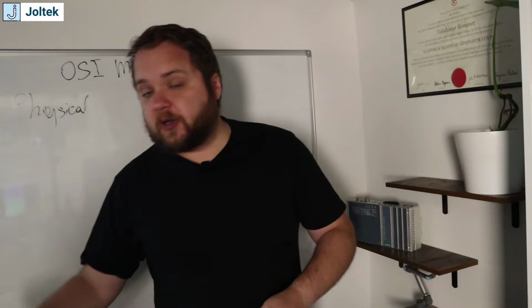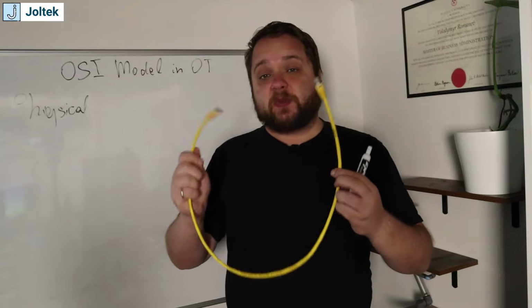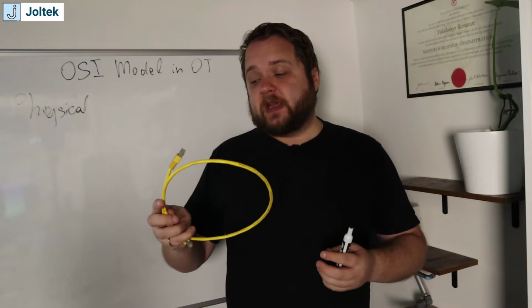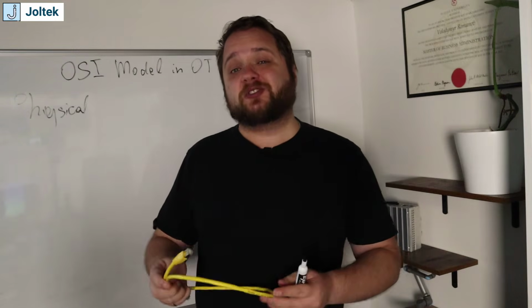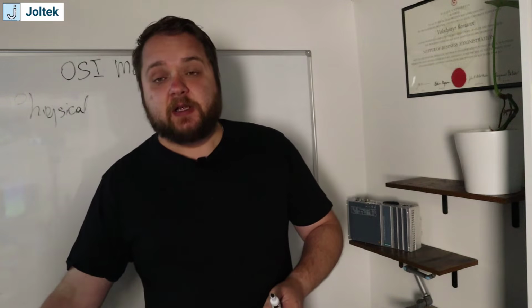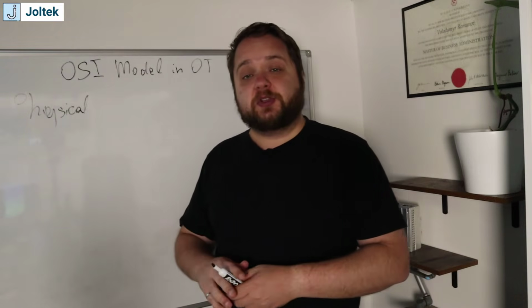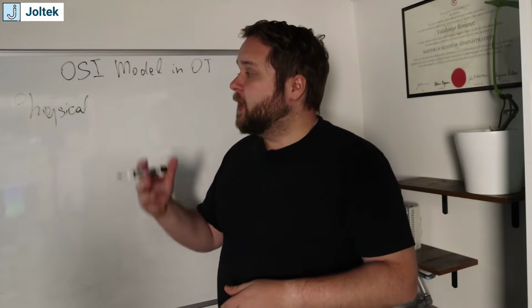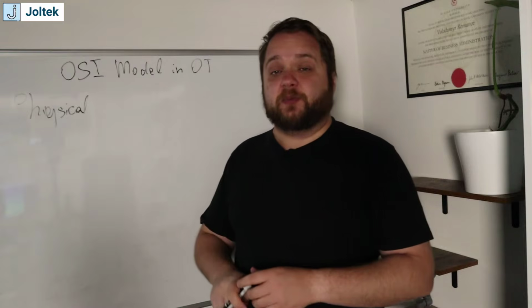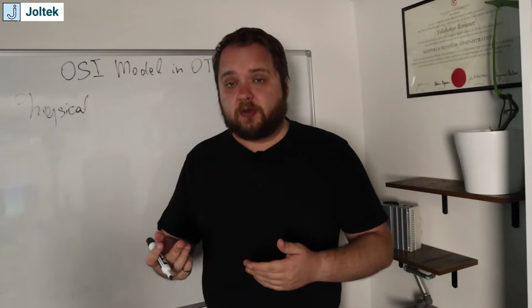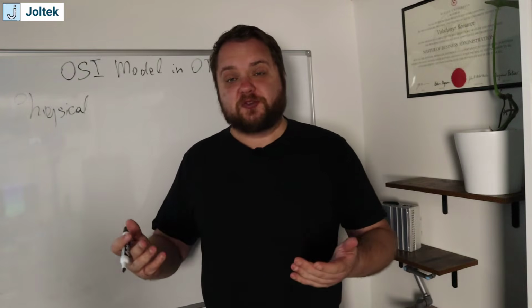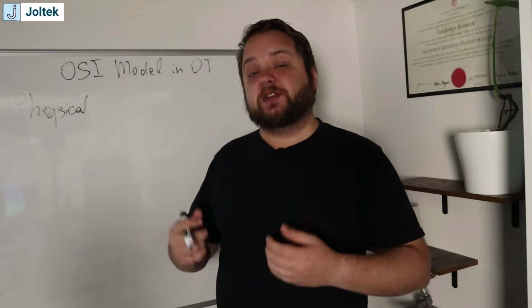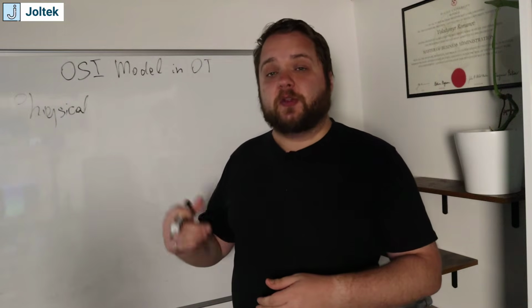And so in a nutshell, when we talk about Ethernet-based protocols, you're going to be dealing with a lot of these RJ45 cables, either pre-molded or ones that you can create by crimping, because you're pulling those network cables through conduit and through different enclosures, unlike the traditional network setting where everything is nice and neat and the physical layer doesn't always get troubleshot. On the plant side, this is very different because, number one, the cables are rarely going to be pre-molded. The cables are usually run next to high voltage lines, which creates noise and traffic, obviously, in the packets, but the physical layer is very important to understand for someone working on the OT side.